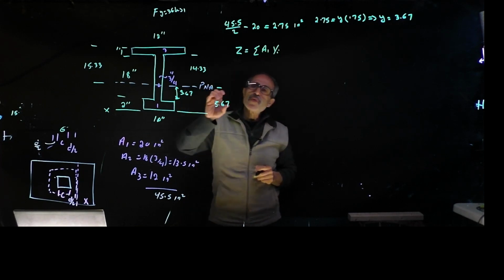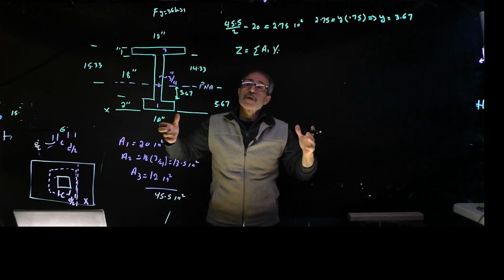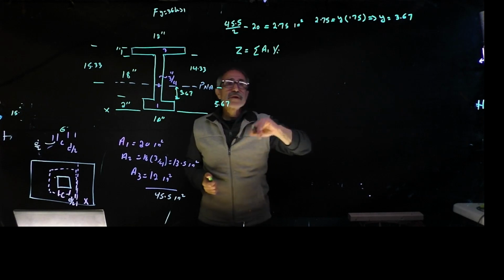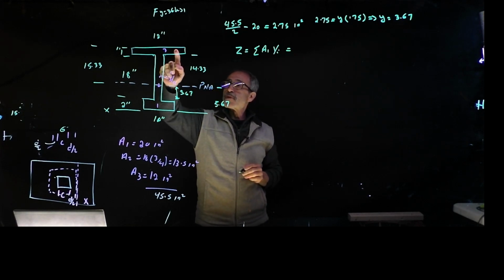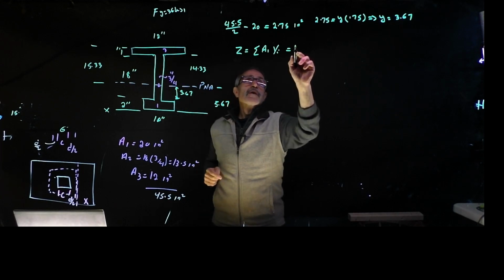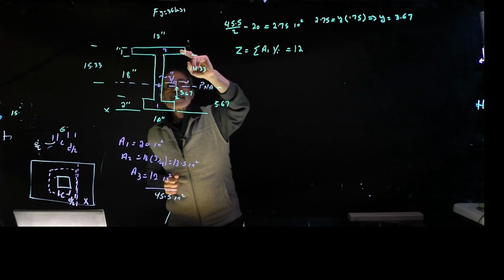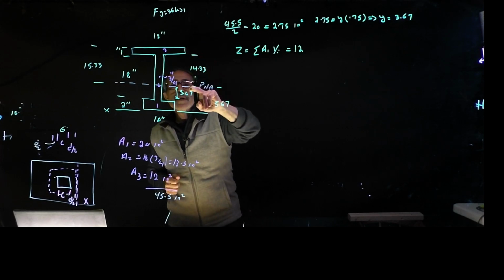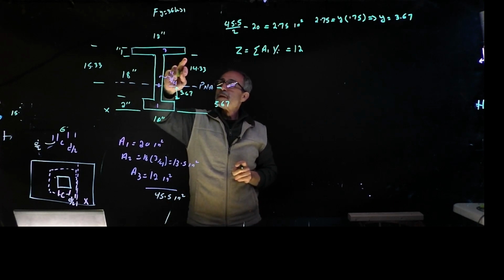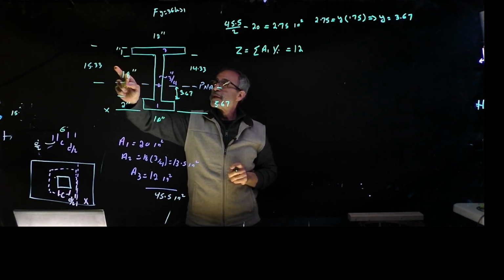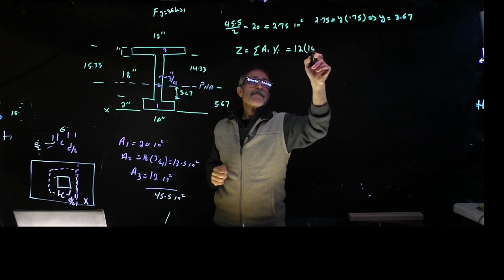Again, you go to your steel design handbook, make sure you know that stuff pretty good, because that's the only thing you're going to have. Study it. All that stuff is in there. All right, summation area. I'm just going to start from the bottom. That was good, 12. And the distance from the center to here is what? If it's 15.33 minus 1/2 inch, that should give me about 14.83.